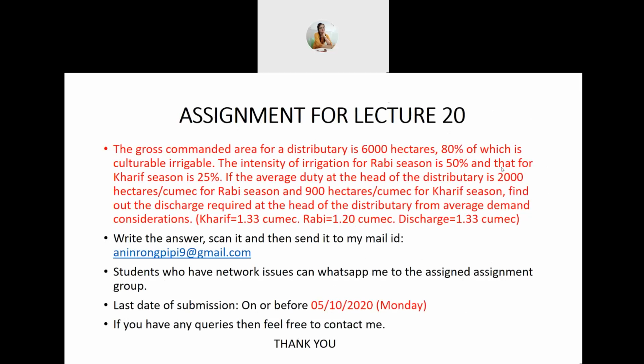So this is your assignment for lecture number 20. The question is, the gross commanded area for a distributary is 6,000 hectares, 80% of which is cultivable irrigable. The intensity of irrigation for Rabi season is 50% and that for Kharif season is 25%. If the average duty at the head of the distributary is 2,000 hectares per cumec for Rabi season and 900 hectares per cumec for Kharif season, find out the discharge required at the head of the distributary from average demand considerations. So the answer is Kharif is 1.33 cumec, Rabi is 1.20 cumec and discharge is 1.33 cumec.